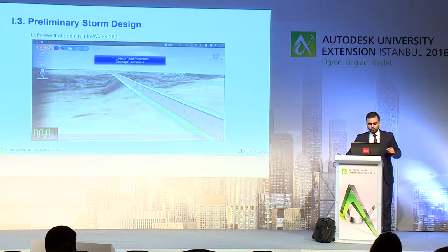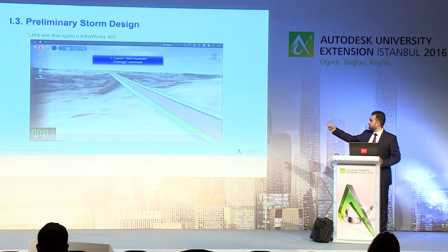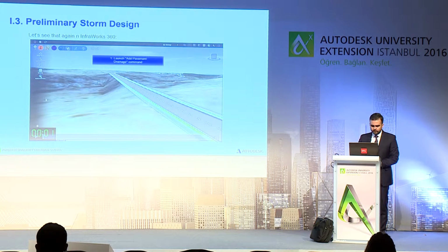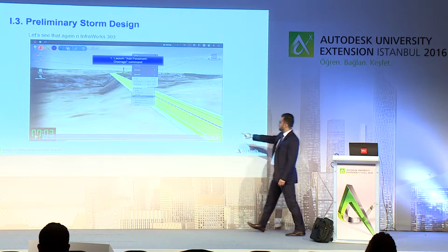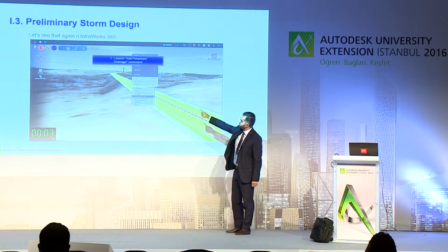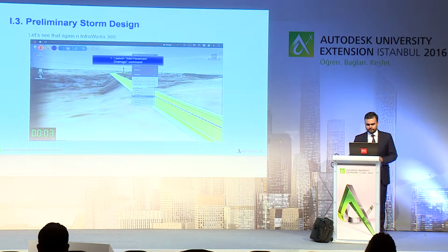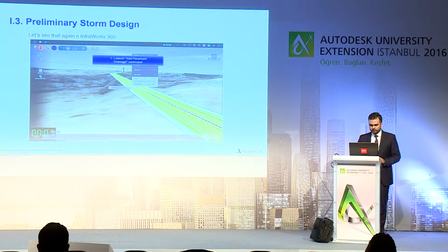So here, for those of you who don't know about InfraWorks, we have the basic features, we have the road and design features and capabilities, we have the drainage, we have the bridge, and this green one is the drainage. So here we can design any storm drainage network on roads. So I'm opening this drainage network, and I'm asking the software to add automatically a pavement drainage command. So just select the road in 3D, right-click, and push on the Add Pavement Drainage option. So basically, 3 clicks.